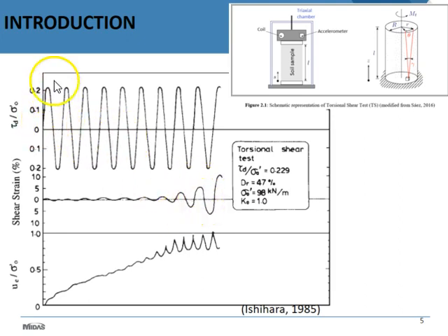If you see, the load is really not going up, but as you load it and load it, what happens in the soil is that the particles tend to reaccommodate. As they do that, the pore pressure goes up, and this is shown here at the very bottom. You have the excess pore pressure also normalized. As you know, if this number goes up to 1, that's when you reach liquefaction. And here, as the number of cycles goes up, you see that this excess pore pressure builds up continuously.